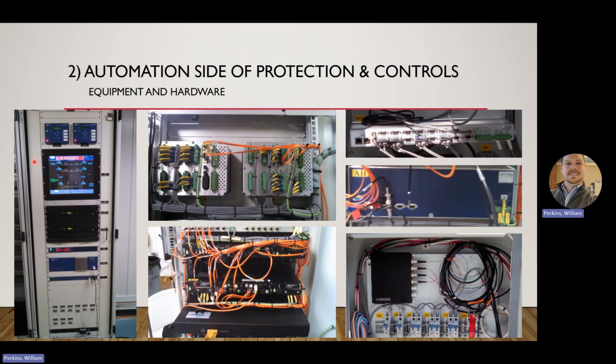Also, the picture to the right here shows the fiber patch panel. The automation and integration group will also specify the type of fiber patch panel and also the fiber ports needed. Are they ST ports, LC, SC type of ports, and again, single mode or multi-mode.